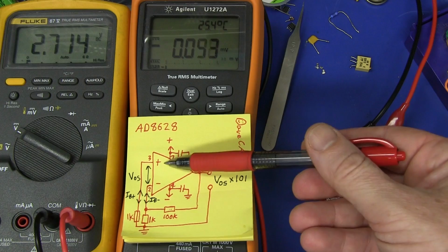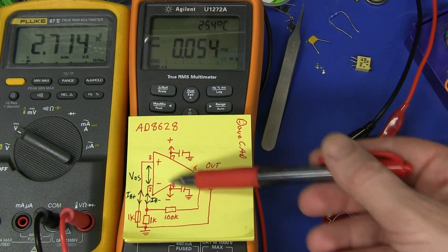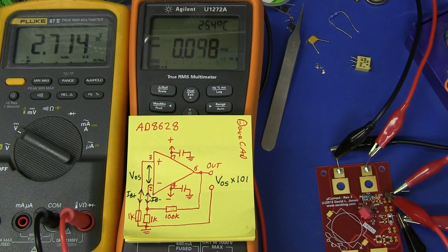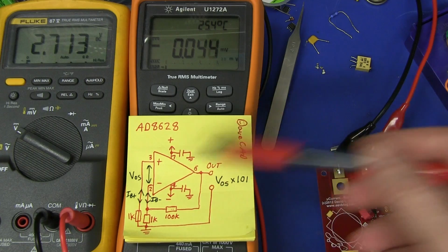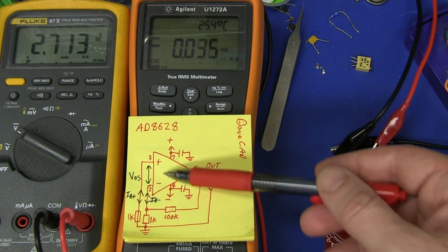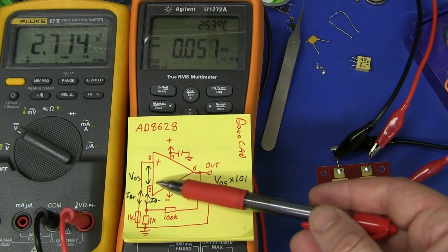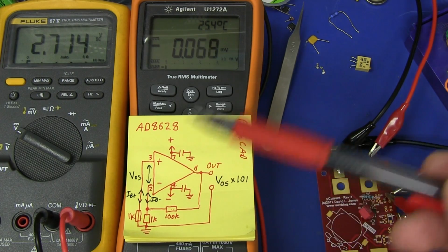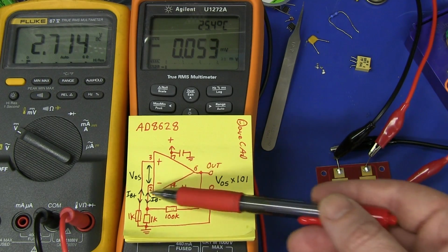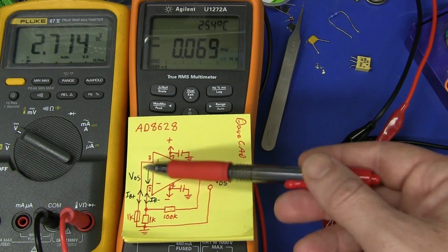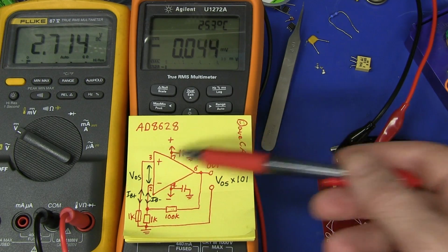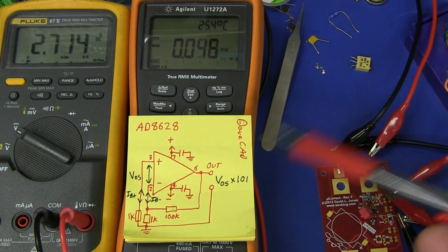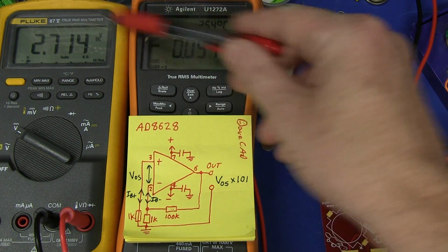So what we've got here is a chopper amp. Its internal architecture is unknown to us. It uses some ping-pong patented architecture that Analog Devices have come up with. It auto-zeros and chops and slices and dices and makes your bread for you and does all sorts of things. So we're not going to get a consistent VOS and input bias currents that can go in either direction for both of the inputs over the supply voltage range here.